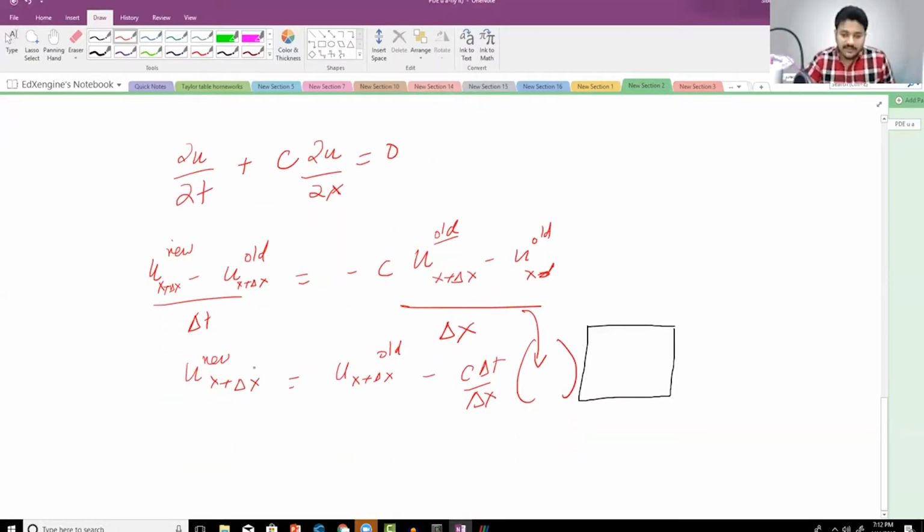So the basic idea is this right here is no longer a partial differential equation. This is actually an algebraic equation. And who is great at solving algebraic equations? Well, your computer is. So you take this equation, you feed it to your computer, it's going to solve it, right? And this is what you call solving the linear system. And depending upon how you structure your equation, you can get a system of uncoupled simultaneous equations or a system of coupled simultaneous equations. This is what you call explicit and implicit. And if you do that, your results are going to change, and you'll basically be able to solve the system, which means you'll be able to get the velocity profile. So this is just for linear convection.